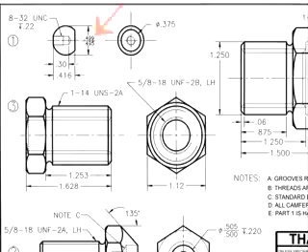The first one we see here is a unilateral tolerance. It's really 0.5 minus 1 thou minus 5 thou. But it's expressed in its limit form, and that's why we have 0.499 or 499 thou and 495. That's just the limit way of expressing it, instead of saying 0.5 minus 1 minus 5.